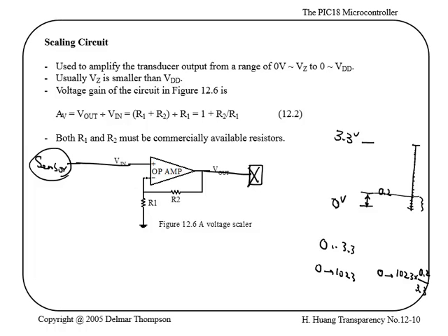Now, the way that an op-amp works is that it makes sure that the voltages here and here are kept at the same level. Okay? And there is no current going in to the op-amp here, right? So the current going in is going to be 0. So essentially what it means is that you have a current I that goes over here, right? And basically when your PIC starts sampling, this I is going to go over there.